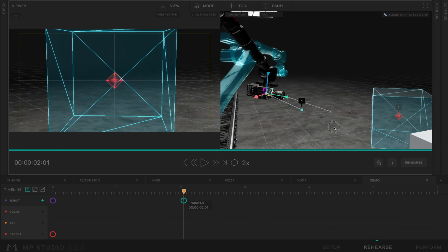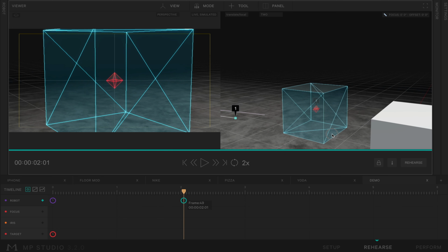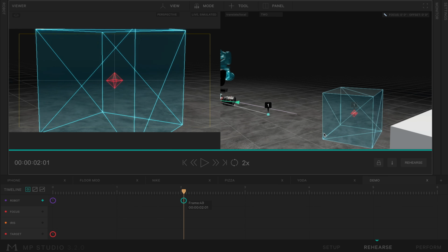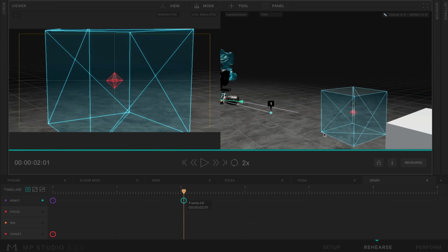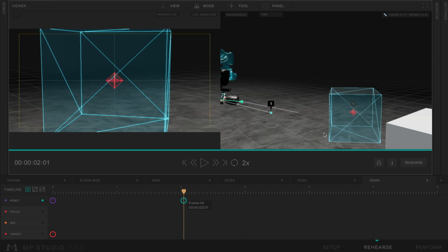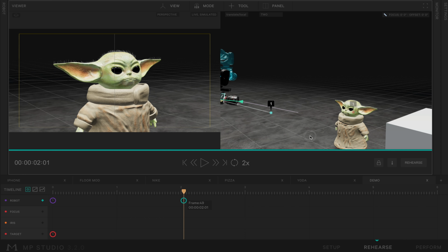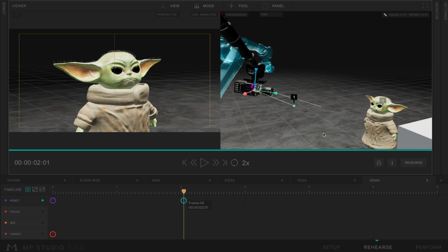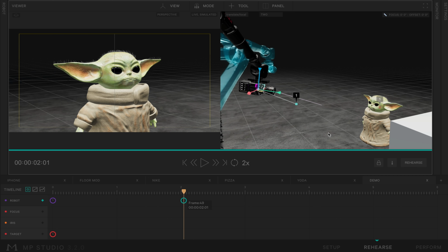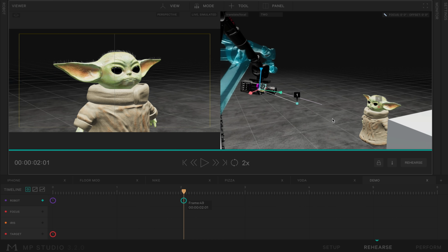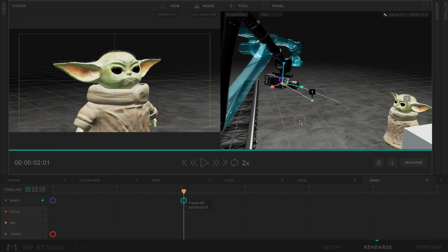You see as you switch rooms, the object has to load up again sometimes, because it doesn't always store in memory yet. We'll look into that in future builds. But these objects can be quite large sometimes. There is a limit to FBX size. I don't know exactly what they are yet, but some FBX won't load if they're too large. So we do recommend the GLB or the GLTF type objects the best. They work primo, but you can also import some FBX objects.